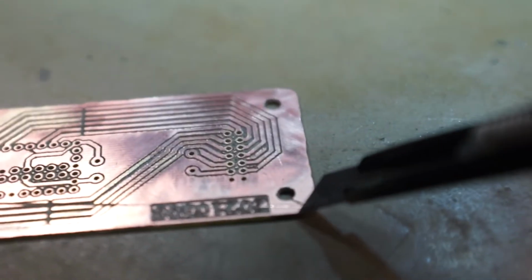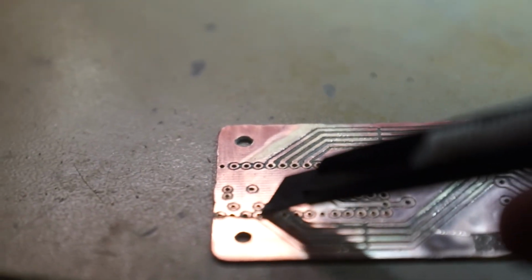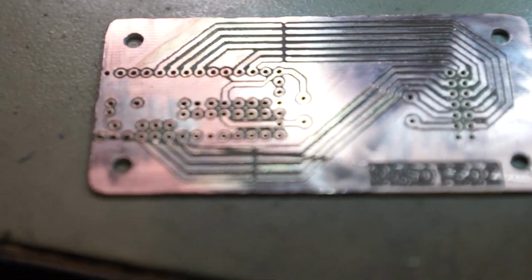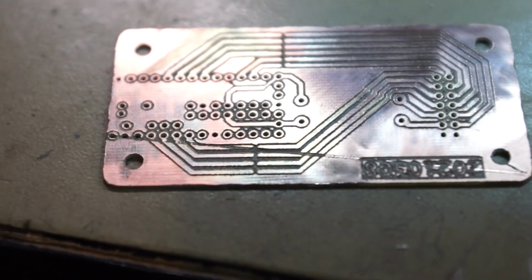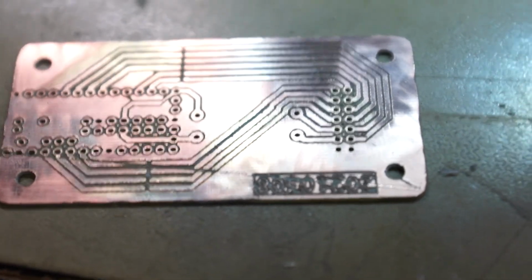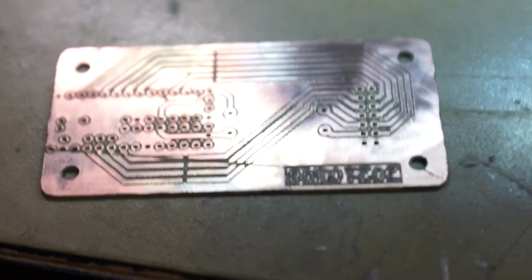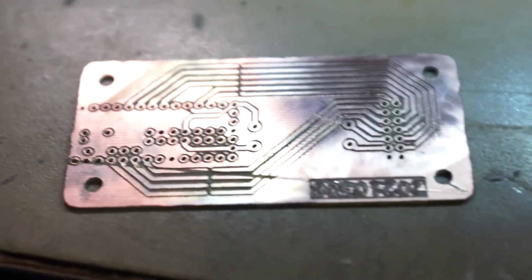Here is a clear defect where I had the drill standing here. The first drill hole was over there, but it was standing at Z0, so it scraped across the board and then started drilling here. So there are a couple of paths I will have to restore. So yeah, some stuff that shouldn't be connected is connected, and some stuff that should be connected isn't connected. So as far as circuit boards go, this isn't the best.